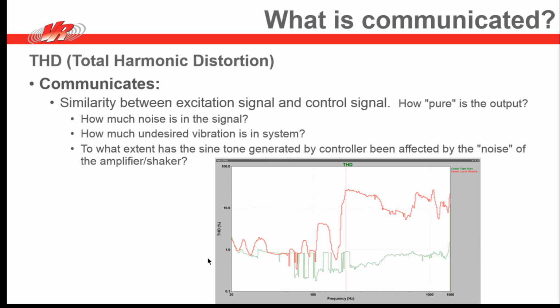The plot we have in front of us here is showing that the two signals that are being compared differ greatly in their total harmonic distortion. This green plot was the shaker head when all was working properly, but if you had a loose bolt on the head expander and there was some warping and vibrating of that head expander, then you did not get a nice replication of the control signal, and there are things that are out of whack, as it were, in a lot of frequencies.